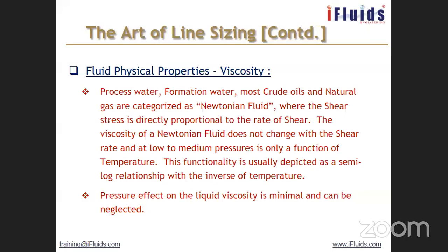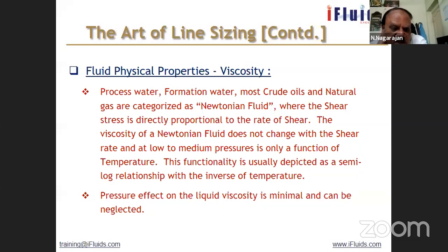Viscosity is a function of temperature. You simply remember, viscosity is a function of temperature. When you increase the temperature, viscosity reduces. Pressure effect on the liquid viscosity is almost nil.